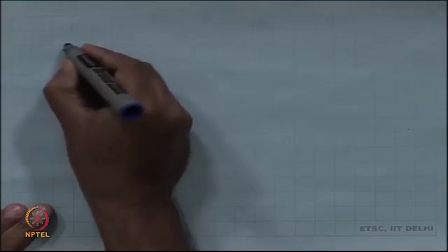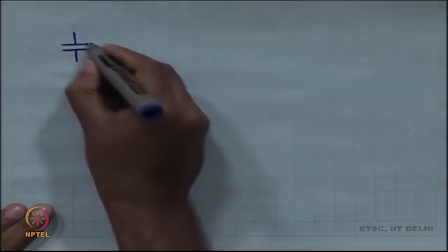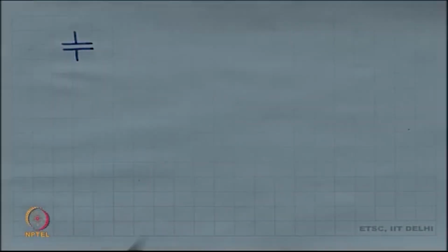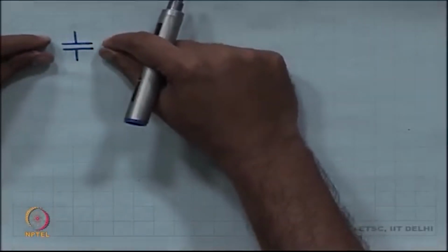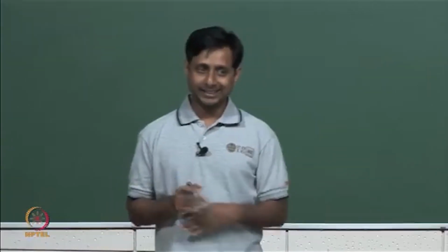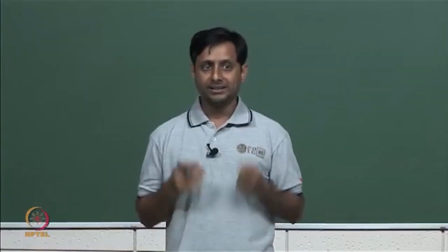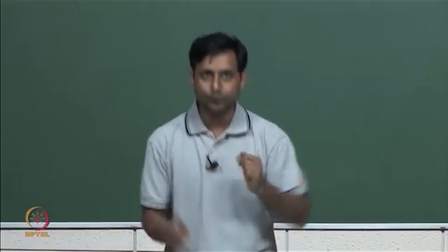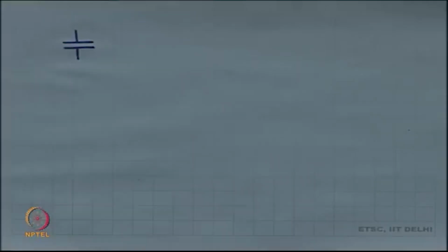The MOSFET is like a capacitor. You are making the thickness of this dielectric thinner and thinner and thinner. In the most modern technologies, 28 nanometer, 22 nanometer, Intel is now at 16 nanometers, this gate dielectric is as thin as a few atoms. It is really thin.